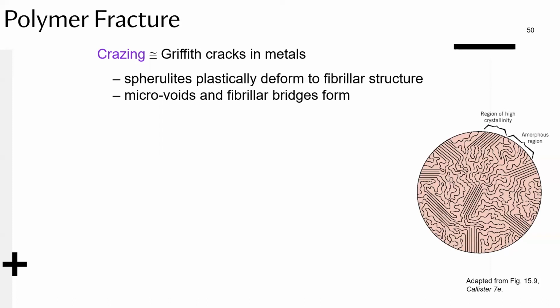So you have some regions with crystalline structure, and in between they're connected with these amorphous regions. The fact that this is the nature of polymers means that it should somehow affect a lot of other things. For instance, we saw that melting doesn't happen at a certain temperature. It happens over a range of temperatures, because of this sort of statistical averaging behavior, where some regions melt faster, some slower.